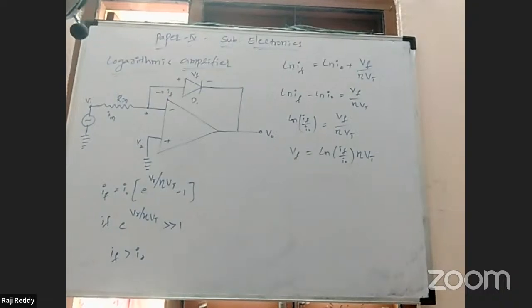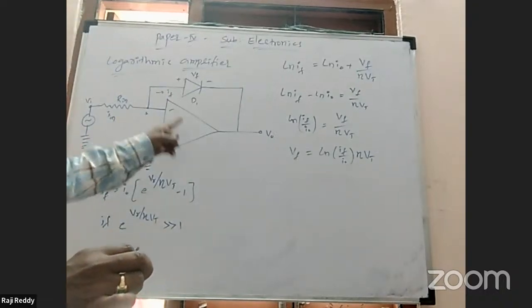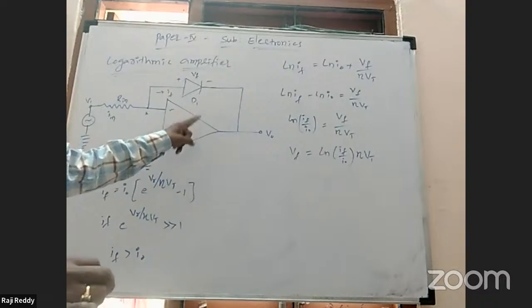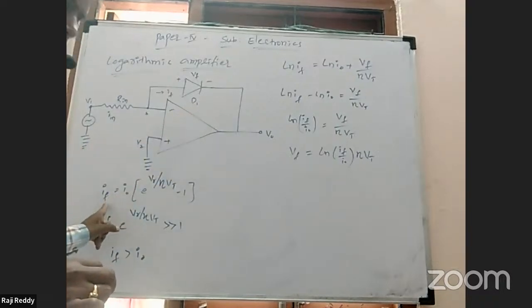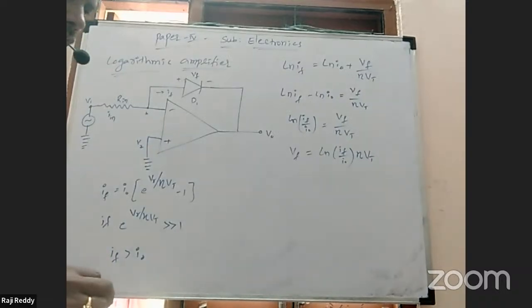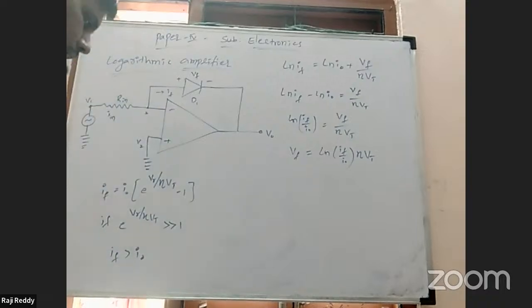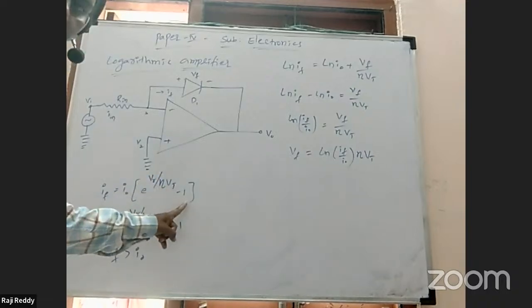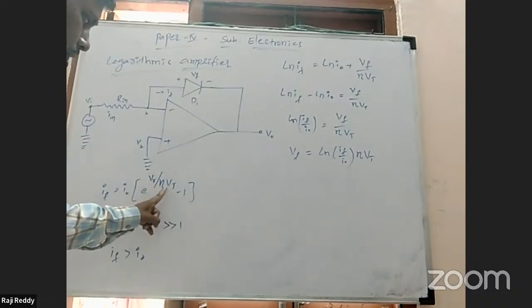The thing is, you can take the diagram and, instead of feedback resistance, you can take the diode, and here there is a current with exponential function. The growing current equation, which we know from the previous years, is I is equal to I naught e power something minus 1. That is here VF by eta into VT.